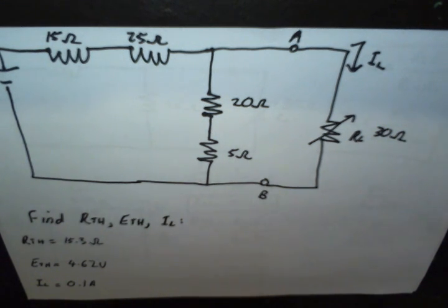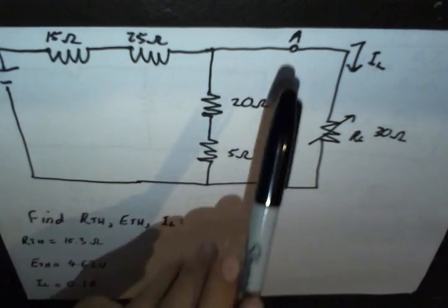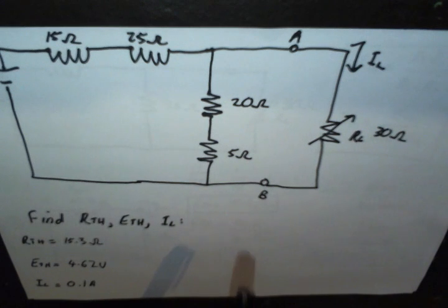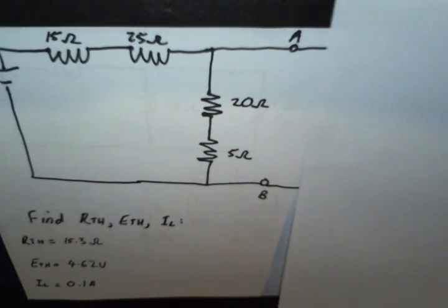of a power supply in series with a resistor. The resistor is the summation of all individual resistances to the left of the open terminals. If the summation is done correctly, the value can be used to find the voltage across and current through the load-bearing resistor. To calculate R Thevenin and E Thevenin, temporarily remove all components to the right of the open terminals, including the load resistor itself.